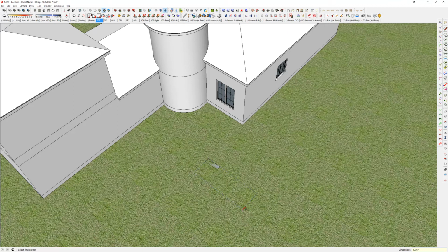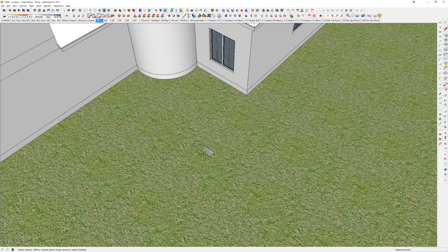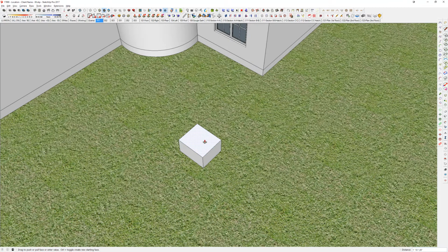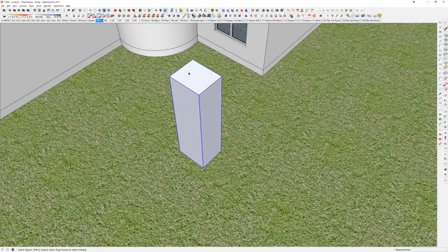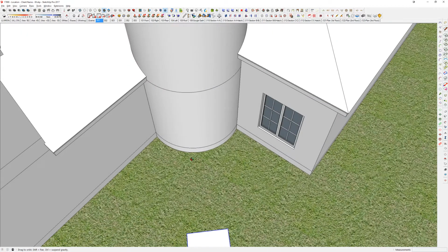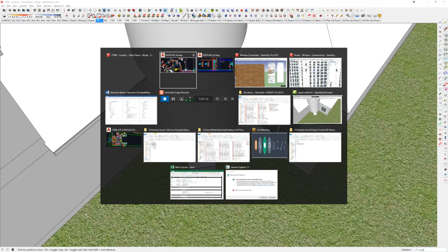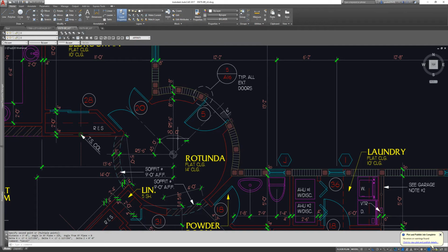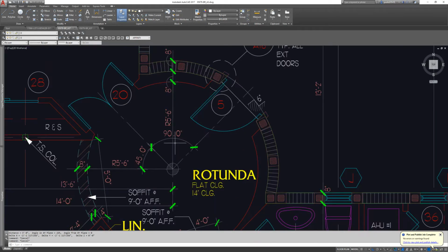And then it doesn't matter the other dimension. It really just needs to be big enough to cut the tower. So I'm just going to make it whatever. I know it's an 8-foot 2 door that actually has a 24-inch transom on top of it. So I just turned that into a group, and I'm actually going to rotate this 45 degrees because from here to here is my 3 foot 4 dimension. And now it's just a matter of where it needs to go. I'm pretty sure it's right at this. Yeah, it's 45 degrees from vertical.